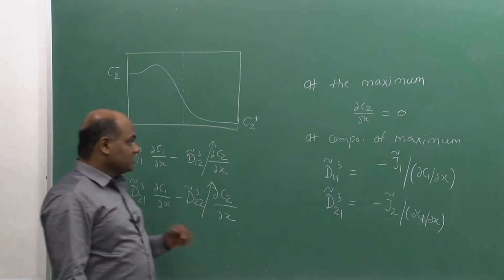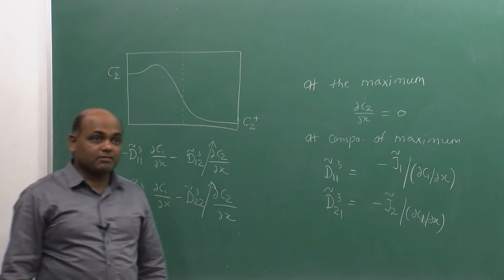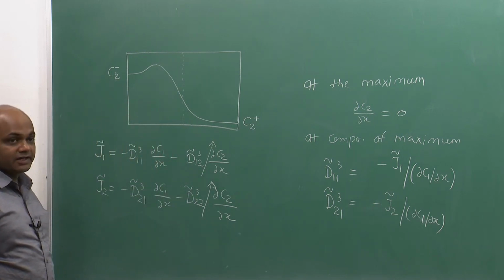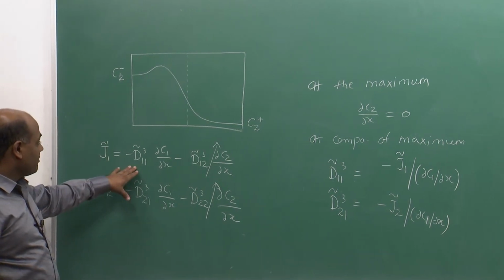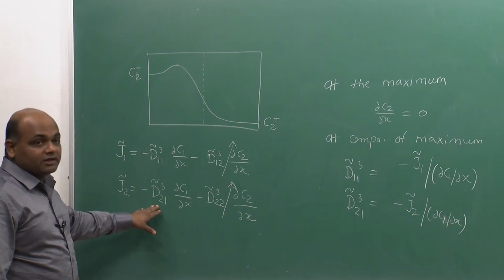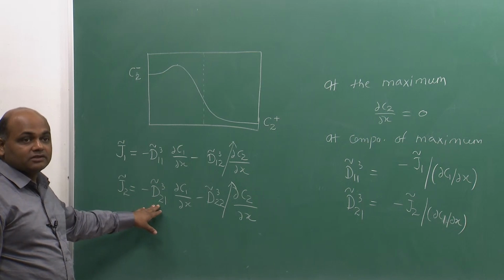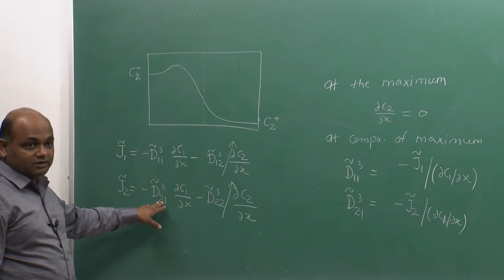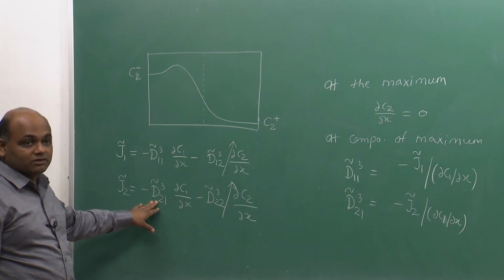Okay. So, this is how we can get interdiffusion coefficient at a maximum or minimum, of course not the entire set, but at least some of them. So, this gives us an idea about main interdiffusion coefficient of 1 and also the kind of interaction that one has with 2, that is how the gradient of 1 can affect the diffusion flux of 2.